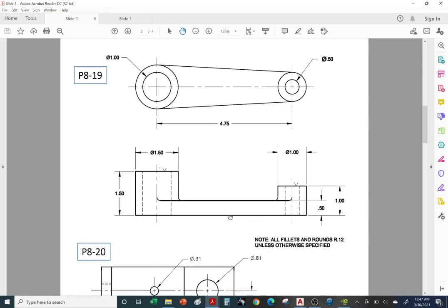That's the reason for the little V, or the upside down V, right? These little V's indicate that this is machined off. So this is also going to have a rough surface. So you come in and machine it off. Right? Same thing with this one. It'll have a rough surface, and at the bottom, a rough surface. So you come in and just machine off a nice planar surface, a nice smooth surface, so it can easily mate up with its other parts, whether it's a vehicle or it can be another assembly other than a vehicle.